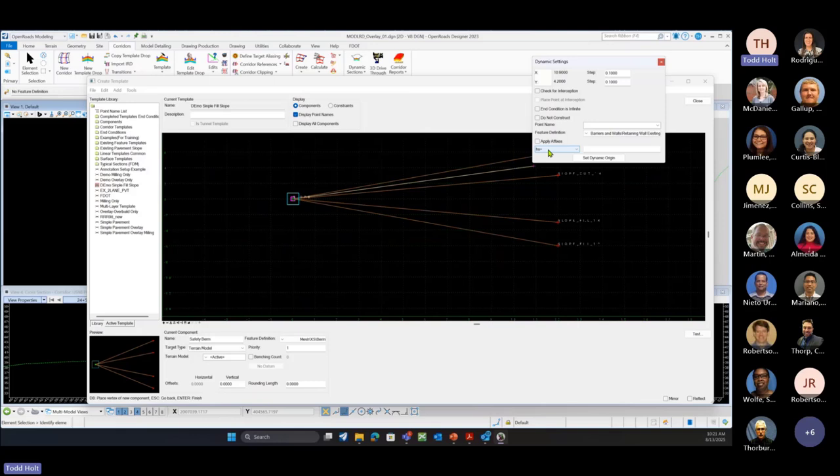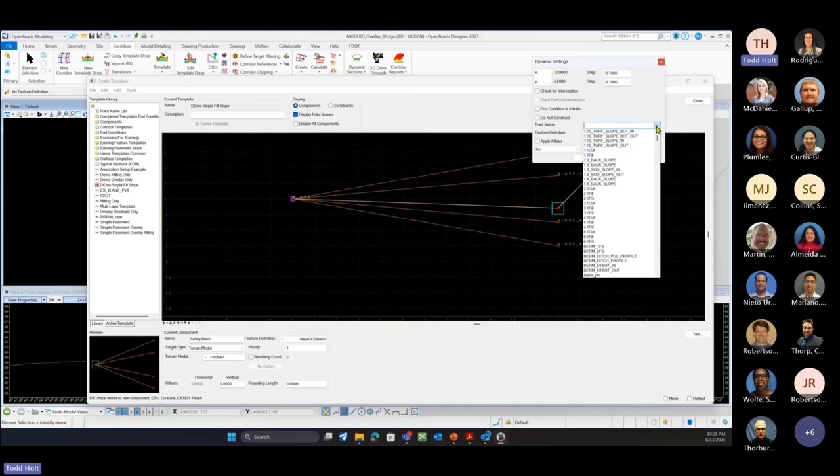And we'll set this to HS. This is going to be a 12-foot berm, do comma, negative 10% or negative 10. And we'll do enter. So there's our berm. And I should have put a point name. We'll come back and fix that.